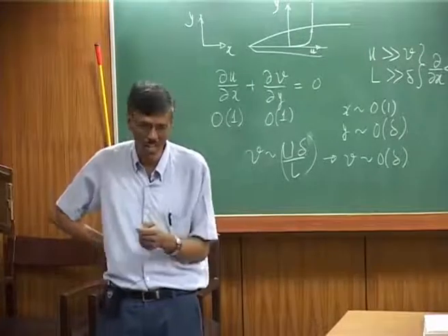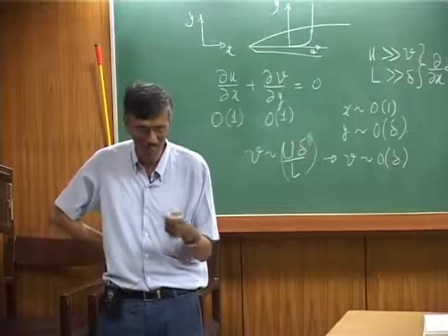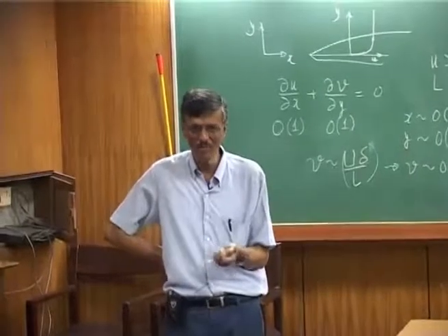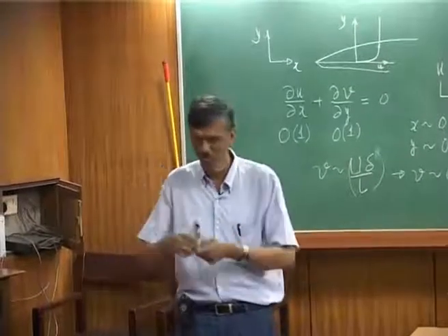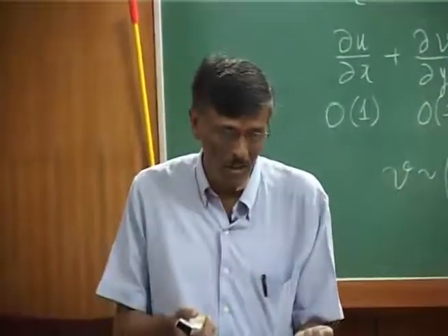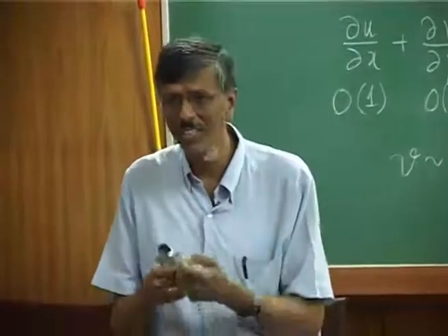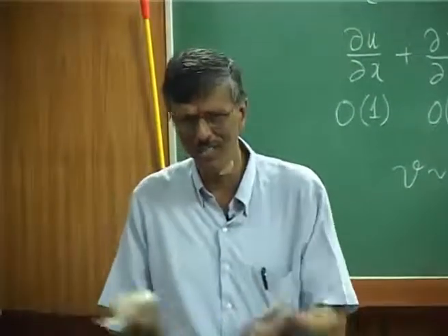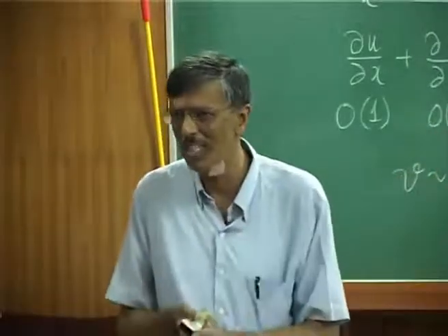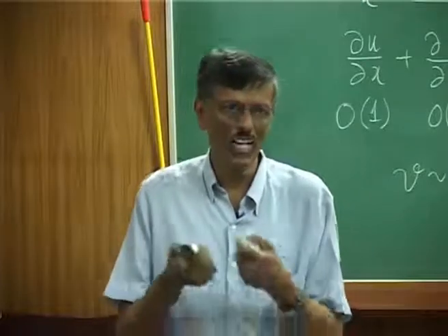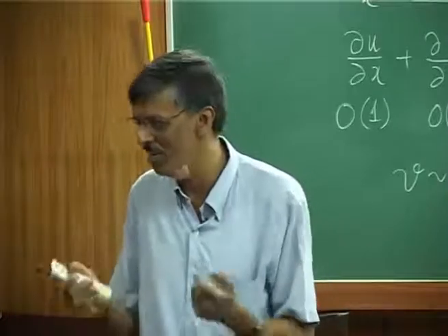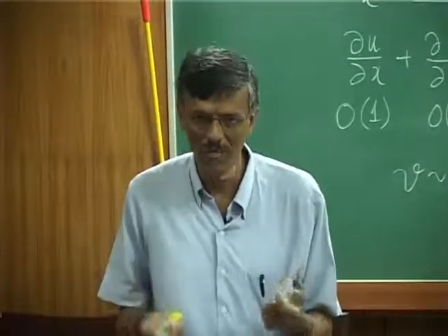So, is it a good thing or a bad thing? As far as problem solving is concerned, it is a very, very bad thing, because you have to take care of all possible modes that would be excited in a system, because they are not damped out. In most other situations, even say an electrical system, ohmic losses are massive, and this quantity in fluid dynamics is such a small quantity that it allows you to retain all the modes, and that means trouble, because you have to be talking about a very, very large degree of freedom system.